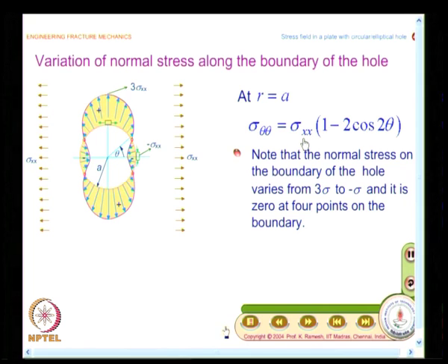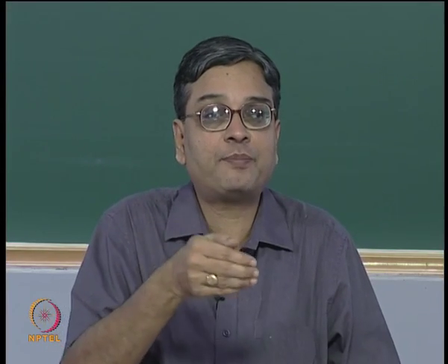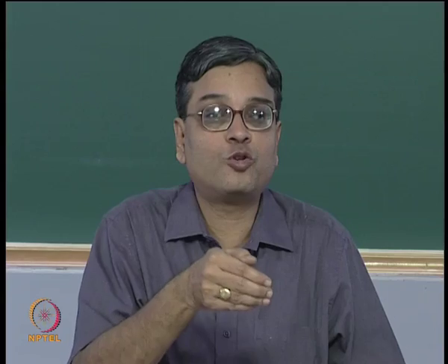See, this is what I had said, when you have a geometric discontinuity, it definitely produces stress concentration. The other observation is a uniaxial stress field changes to biaxial stress field near the vicinity of the geometric discontinuity. And when you really investigate the stress field, you also have surprises. When I apply tension, there are also compressive stresses that could be developed on the boundary of the hole.